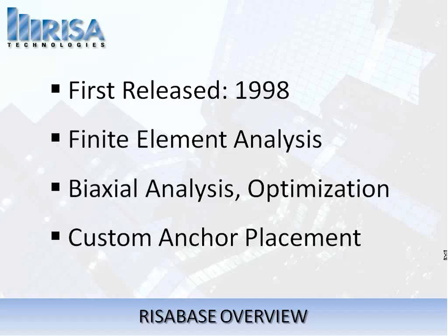Now, one interesting thing about RISABase that really sets it apart is that it's a finite element analysis-based program, and it's doing full biaxial analysis and optimization. So it really goes a step beyond the basic hand calc methods that you get out of the AISC, which are going to assume rigid plate behavior.